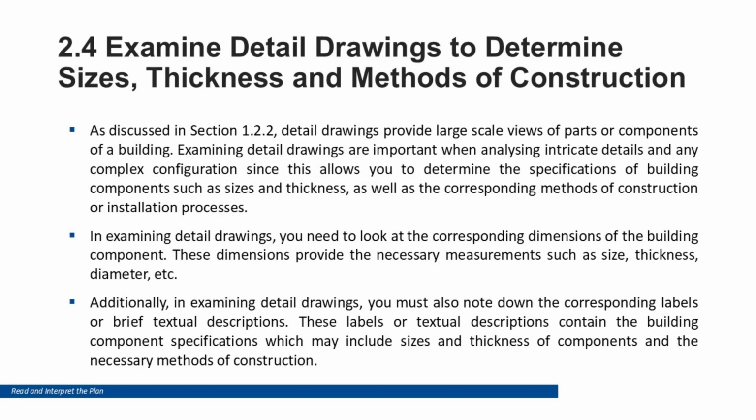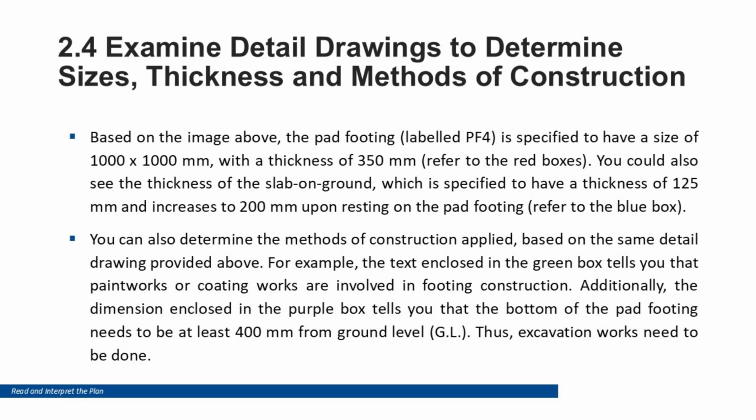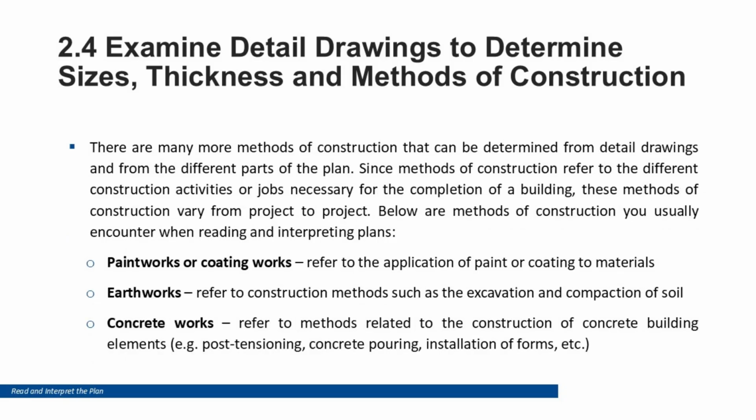Detail drawings. Detail drawings provide enlarged views of specific areas where standard plan scale cannot show sufficient information. Details commonly include stair construction, wet area waterproofing, balustrades and handrails, window and door flashing, corners, junctions and connections, footing and slab cross-sections. A detailed drawing may include notes identifying materials, installation methods, fixings, membranes and tolerances.